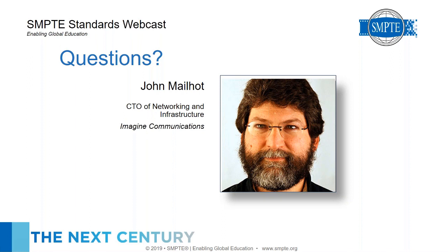Next question. Do engineered networks, as noted in TR-1001, accommodate geographically distributed endpoint sources that contribute to a central facility? They certainly could, but if they're engineered, I think there is probably some point of scaling at which it's wiser to treat the facilities as separate facilities, and it may be related to PTP timing and whether you treat things as one large PTP domain or as separate domains.